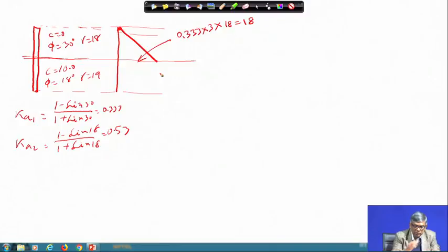and now this will be acting as a surcharge, but now when I will be doing this layer, I can forget about the presence of this. Now, if I assume from here, and then c-phi soil, you know P A will be equal to gamma H K A minus 2 C root K A. Okay. So, here what I can do now